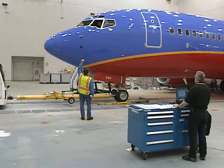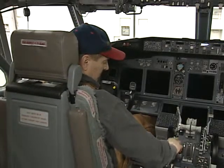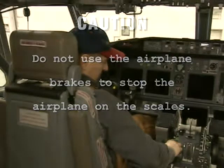Once the airplane has come to rest on the scales, set the parking brake. Caution: do not use the airplane brakes to stop the airplane on the scales. This could damage the scales or induce side loads on the scales, resulting in erroneous readings.